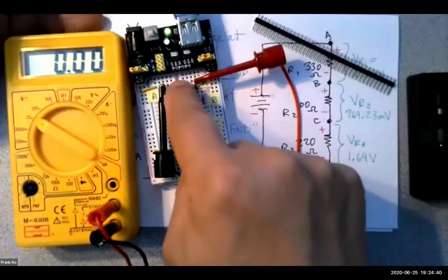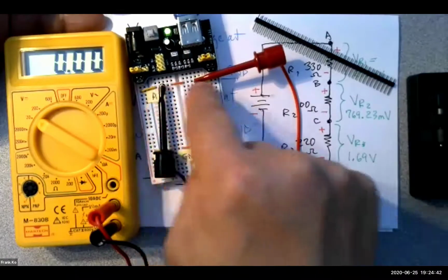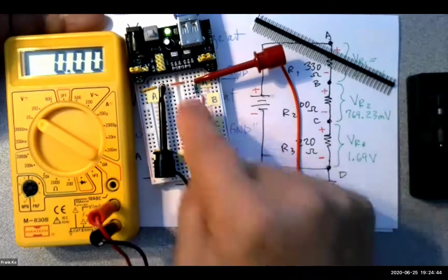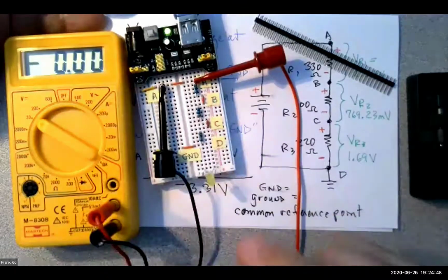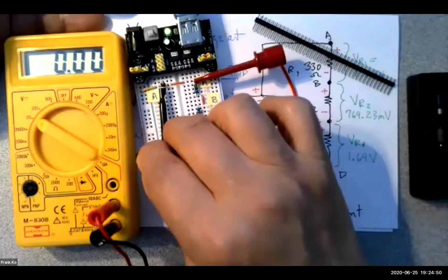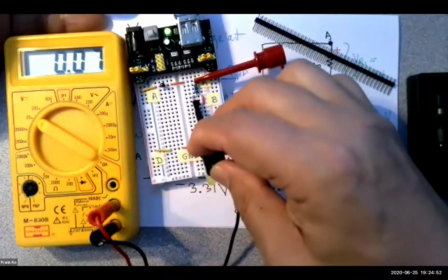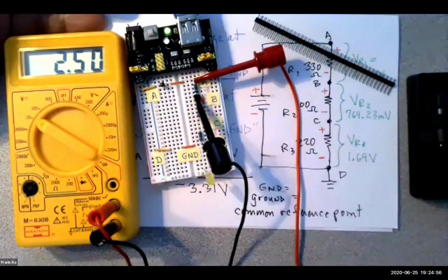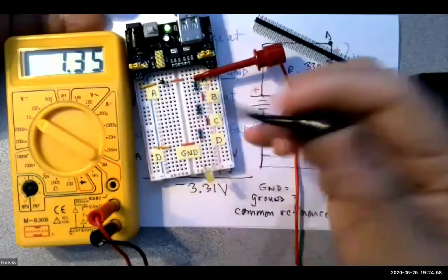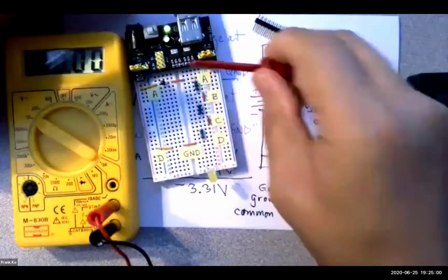So when you're measuring across a wire, you're measuring no resistance. If there's no resistance, there's going to be no voltage drop. And it should be 0 on any wire. The only time you're going to have voltage is if there's a difference of potential, as evidenced across R1 and any of the other resistors. Okay, so this might help you out on that homework exercise.